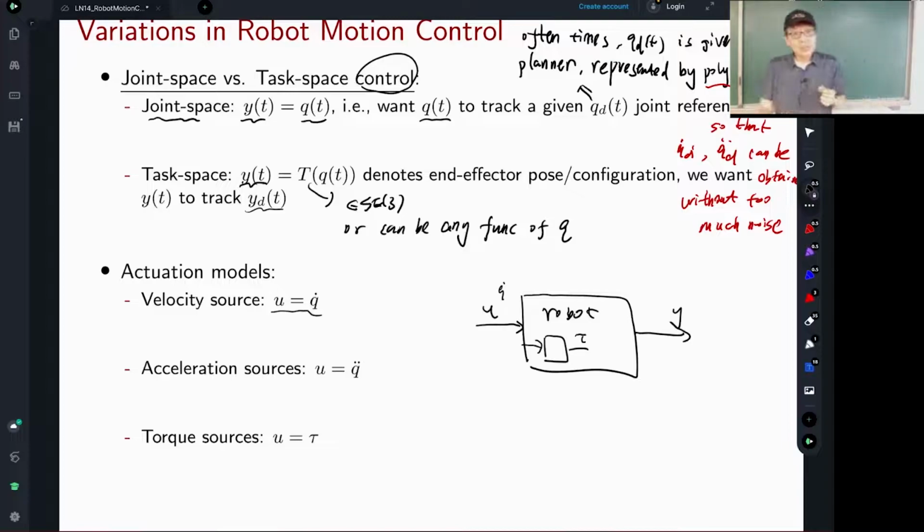That's kind of important. Let me go slowly to make sure you understand that part. If you gave me an industrial robot, oftentimes you can directly only specify the joint position. Maybe not even velocity that easily. Typically you can tell them, okay, that's the position of each joint, you should move there. That's maybe fine, but you typically cannot directly control the velocity.